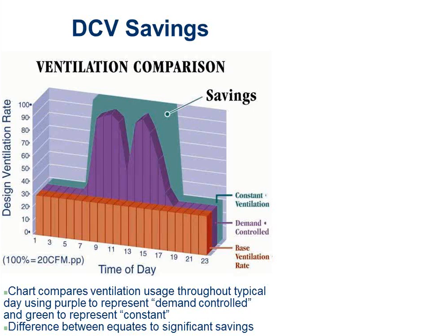So I figured out the regular code said bring in a certain amount of air. Let's just say, for sake of argument, 1,000 CFM. Great. 1,000 CFM is what I got to bring in. So what is this here? 7 o'clock in the morning, we turn the system on. I provide 1,000 CFM of air per the regular ventilation code. And then, what is this here? Say 6 p.m., we shut off the ventilation system.